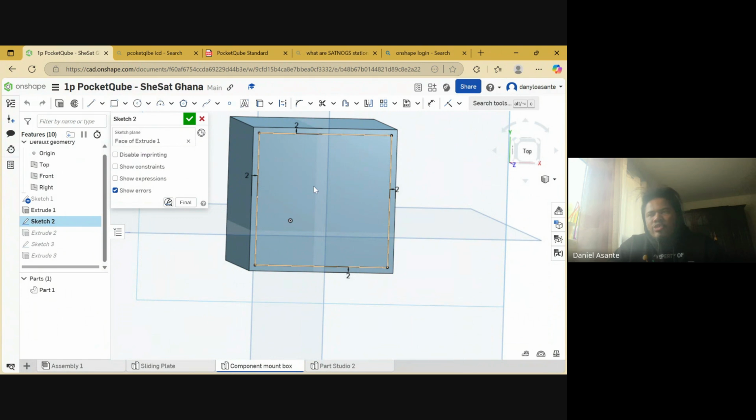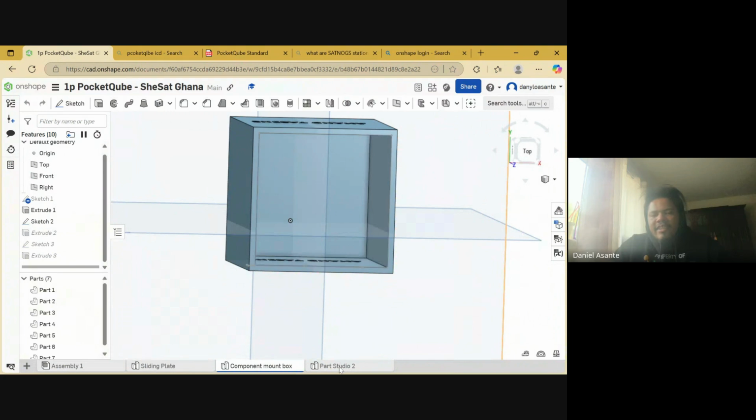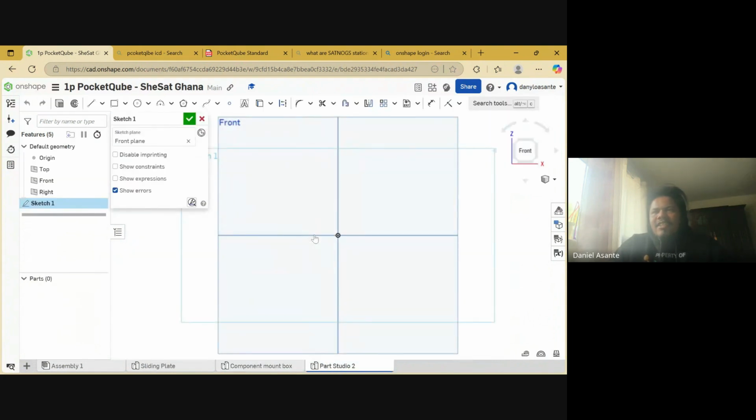So it means that we need to size our cover in such a way that it is less than 46 millimeters so that it will fit. Because if you size your cover exactly 46, it would sit on top of it, but it wouldn't enter, right? So you need to make it slightly smaller so it can fit inside. So usually you can set a tolerance level, right? So you don't want it to be too small or too big.